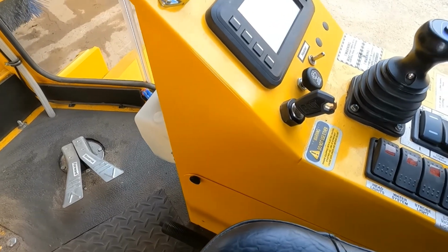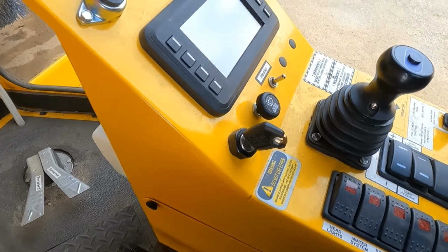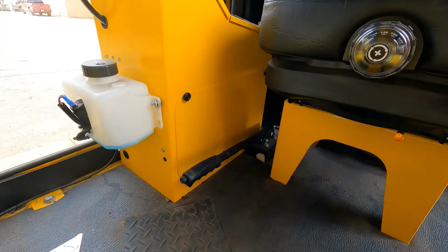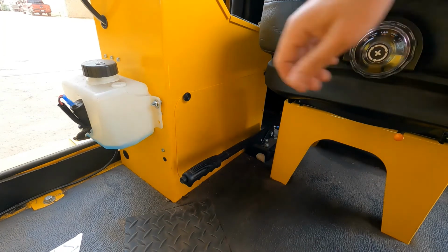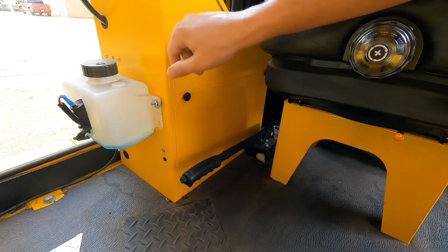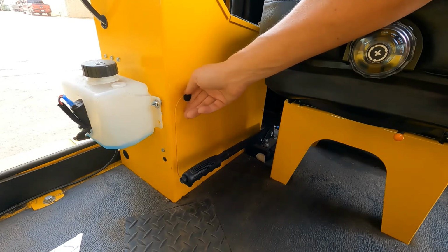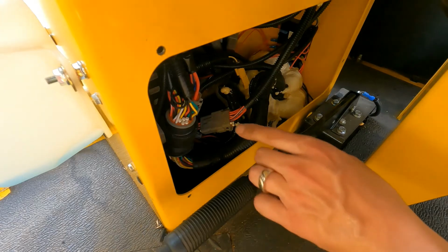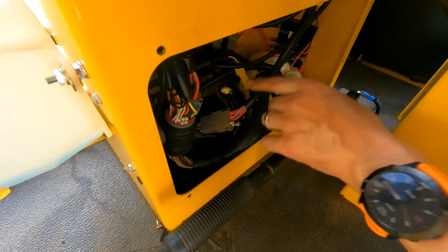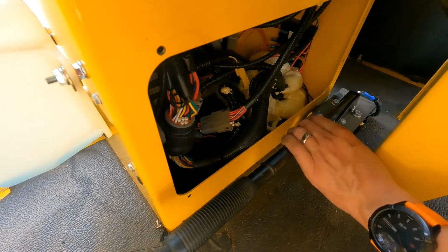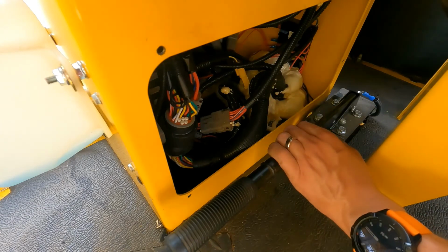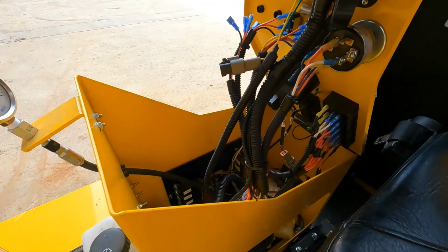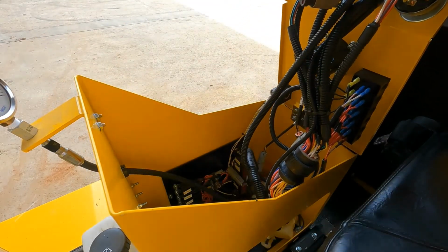Hello and welcome. In this video, I'm going to show you how to connect your new Applied Fluid Power Connect IoT system to your machine. The first thing you're going to want to do is find access to power, ground, ignition, and any CAN buses, typically found underneath the access panel just like this. On this machine, you can see that we have access to several different CAN bus networks, power, ground, and ignition. This would be a good place to start. I'm going to open up the top of the operator control panel here, just so I have a little bit more room to do my wiring.